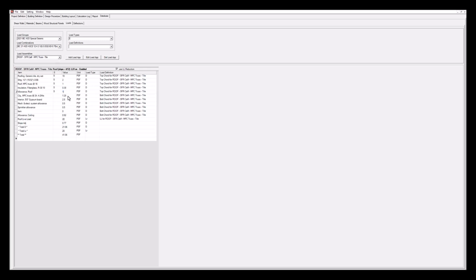So let's go ahead and make the same adjustments, kind of similarly, 1.5. If I make all of these maybe different adjustments to the names, I can adjust them. Whatever is important to me, then I say apply changes. It will then calculate those for all of the dead load and live load. It will keep these changes, and I can toggle through a few of the ones that are important.